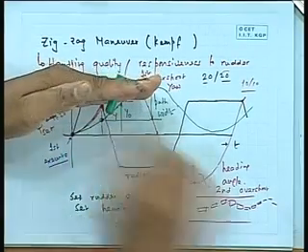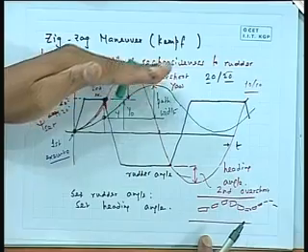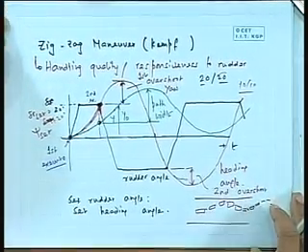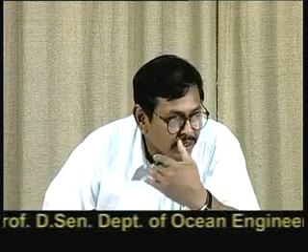How much does it overshoot? Think of a canal. This is the canal size. It has come here. At that point, I have given a rudder back, so it should have come down. But instead of that, it kept on going some more distance-wise. So always, overshoot is the maximum that it has reached from the time when the rudder has been reversed back. In a car, when rudder is reversed, instantly the ship would turn on the other side. It does not happen for a ship. It keeps on going in the same direction for some more time. That is what is called overshoot. So this is my first path width overshoot.